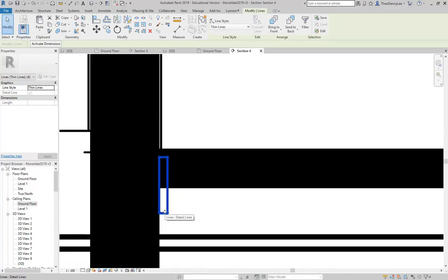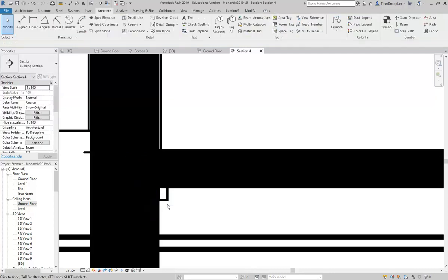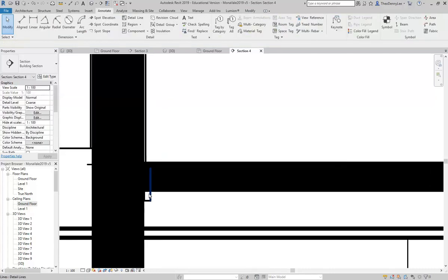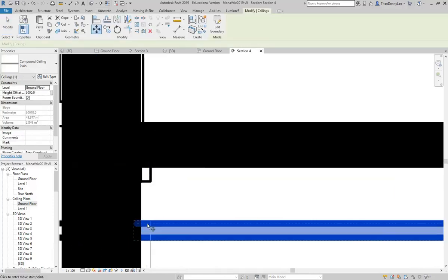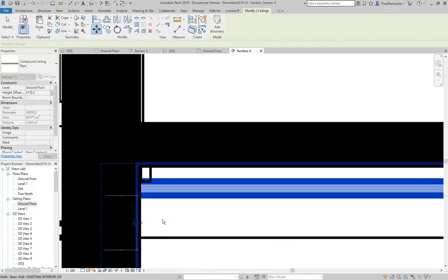So they'd be something like that, and let's see what's that depth there. That's too much, so it might have to be LVLs to span. Oh no, they wouldn't even be LVLs. So probably about 200 at most, maybe even 150. And that's it. So then the ceiling could go up to there.